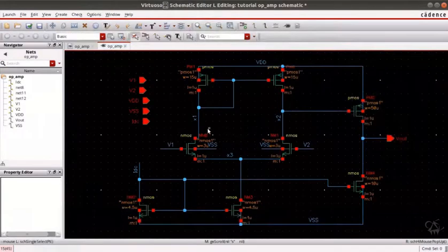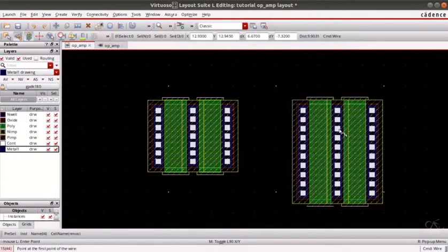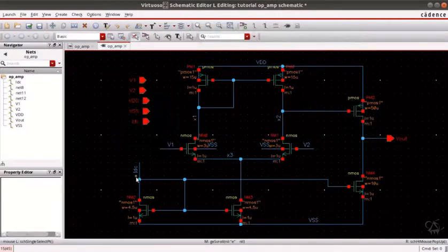So coming to the NMOS, this is X3, VSS, IDC. So IDC, two transistors. So again these two gates are shorted, and it is shorted via metal 1 to IDC.